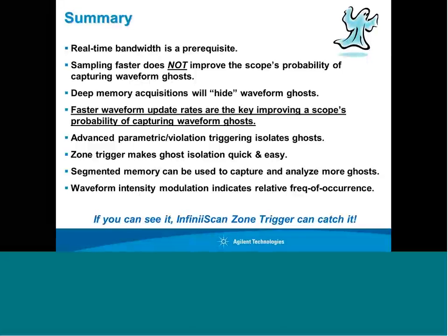In my opinion, the number one criterion is bandwidth and sample rate. The number two, most important criterion of any scope, in my opinion, is waveform update rate if you're trying to debug and solve problems.